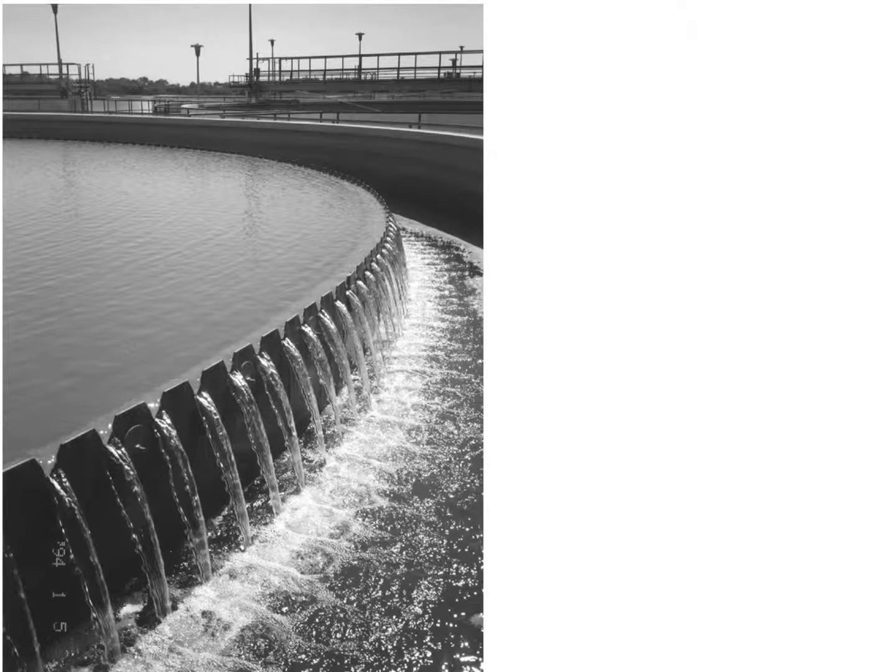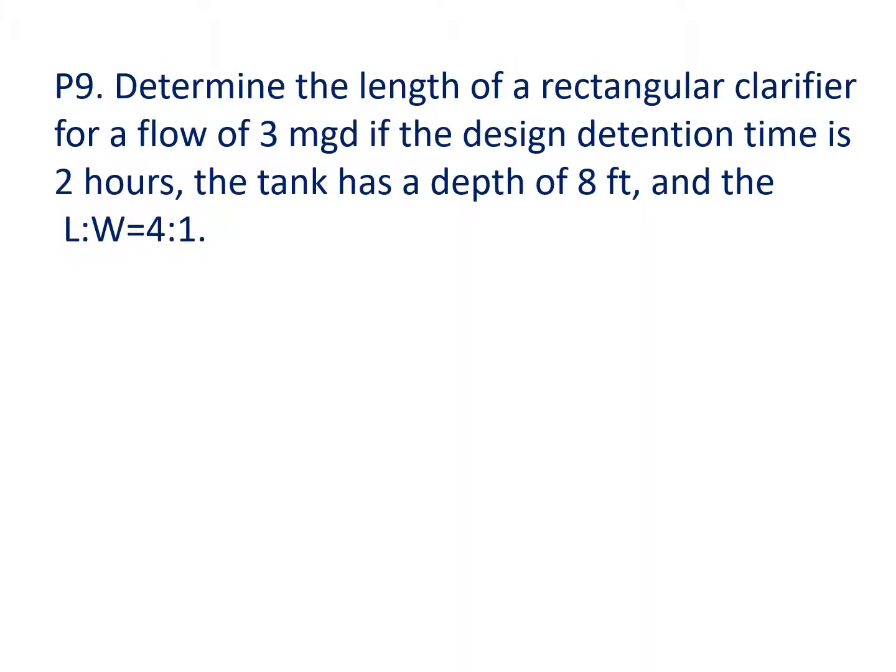Here again is another picture of a circular settling tank, with steel V notches. The water flows freely to the sides, and you collect it from the sides at the V notch. These are weirs that you need to design based on this formula, the same as for weirs that we did in fluid mechanics class.